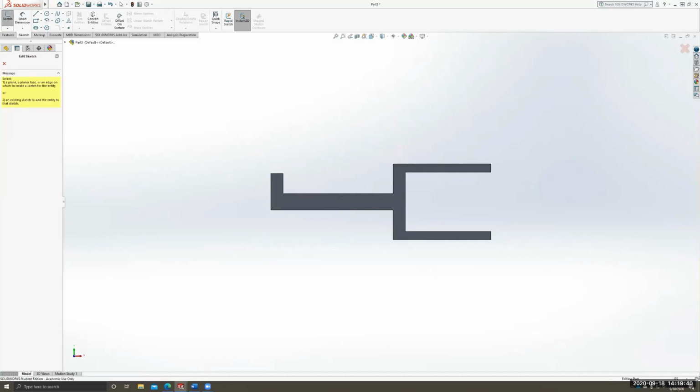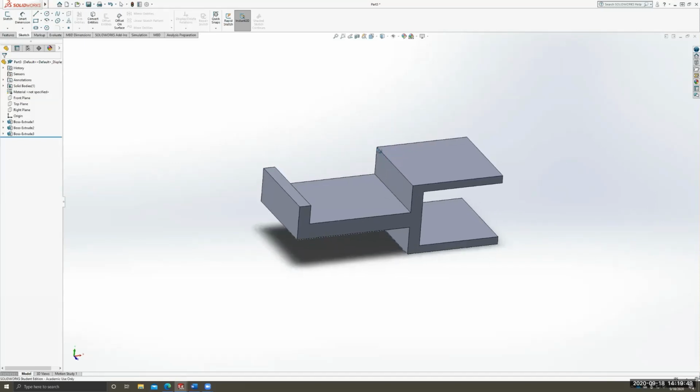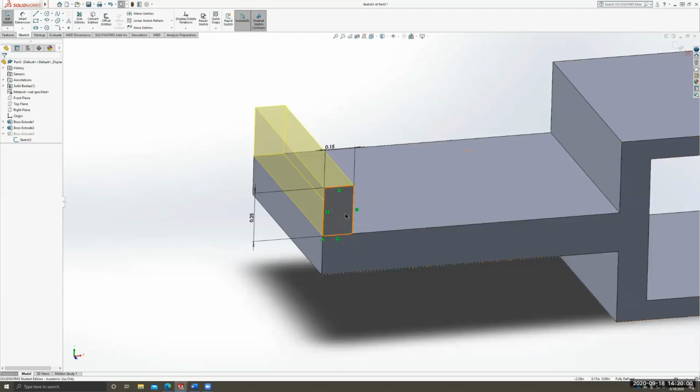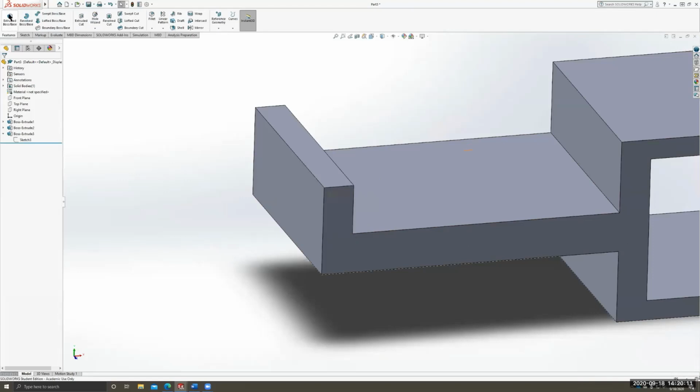How did you get the drawing from 2D and then change it to 3D right at the beginning? Yeah, so you mean from a sketch to an extrude? Yeah. So in Sketch, let me edit it. In Sketch, we have this 2D plane. It's gray, right? So you can go to Features. I already extruded it, so it's blocked out. Right here in Features, this is Extrude. I'm going to extrude something, and that'll be how you get it to 3D. Okay, gotcha. Nice.